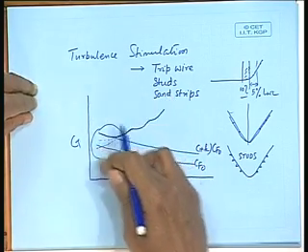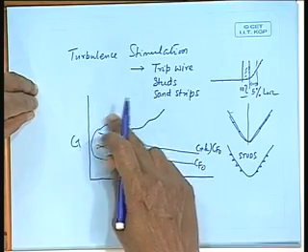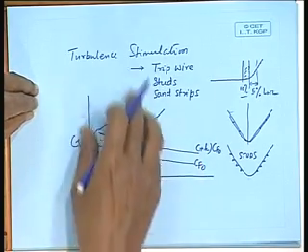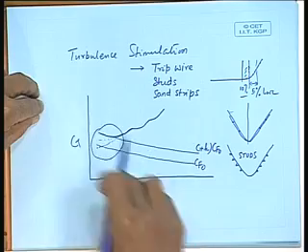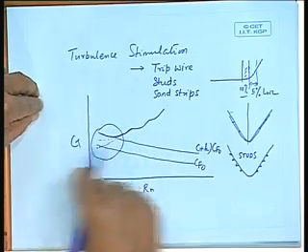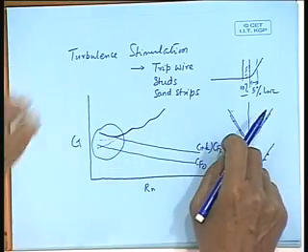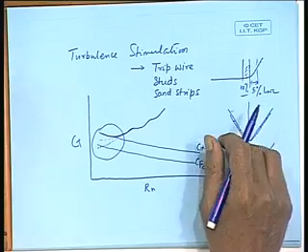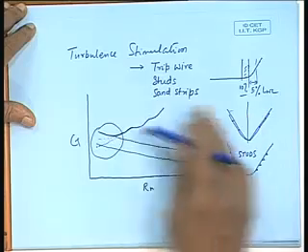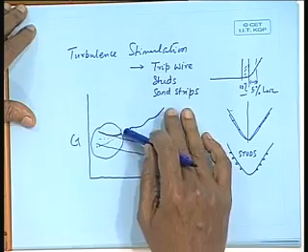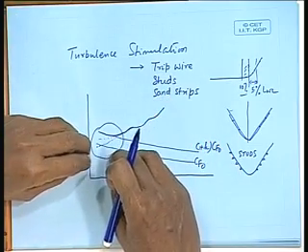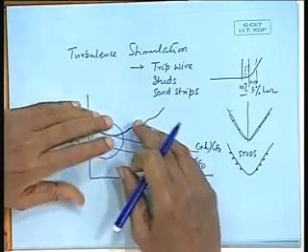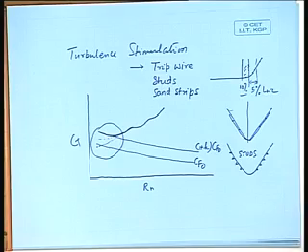So, the error part of the model experiments shows mostly at low speed region, whether it is Rn, Fn or speed, whatever we plot the graph with. If there is an error, it shows mostly at low speed, and therefore, as I mentioned before also, the estimation of k itself and the nature of the curve here is always a little suspect, and this suspicion reduces if you go for bigger models in a bigger tank.